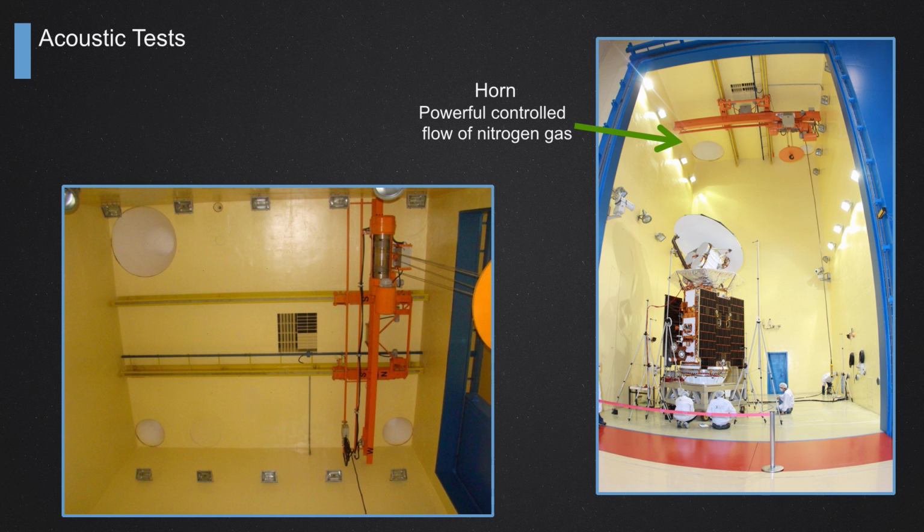Okay, this is just a picture showing the acoustic chamber. You can see inside, at the right, the spacecraft installed inside a cart. The technicians are preparing the test. You can see around the spacecraft some stands holding the microphones that will ensure the level of vibration takes place during the tests. Again, the spacecraft has a lot of sensors installed in its structure to measure the response, the results of vibration in the spacecraft. Okay?